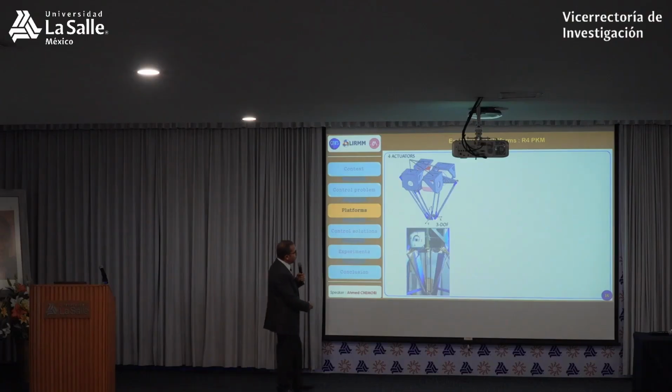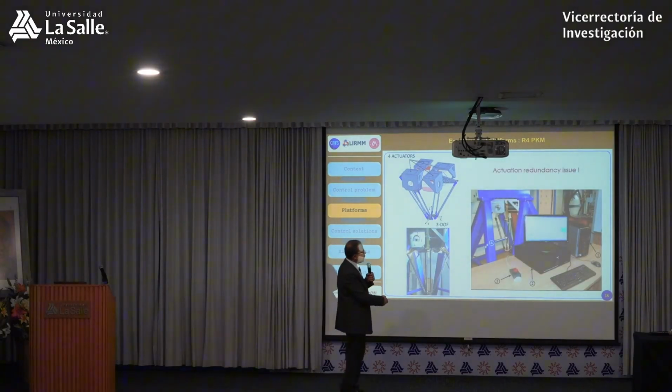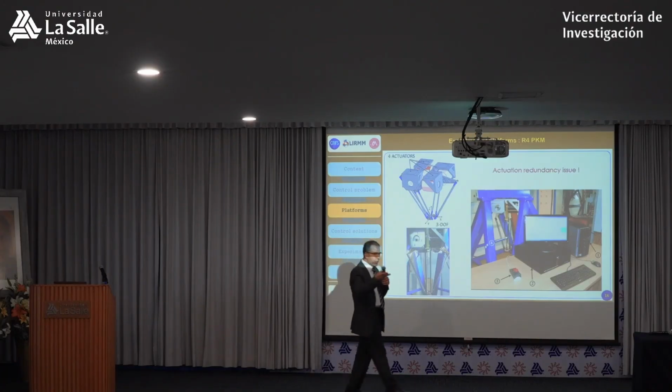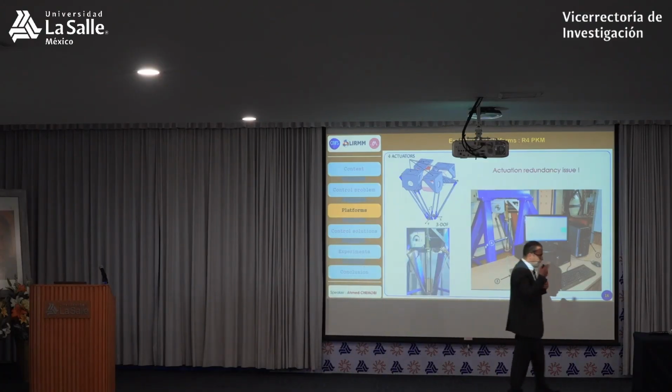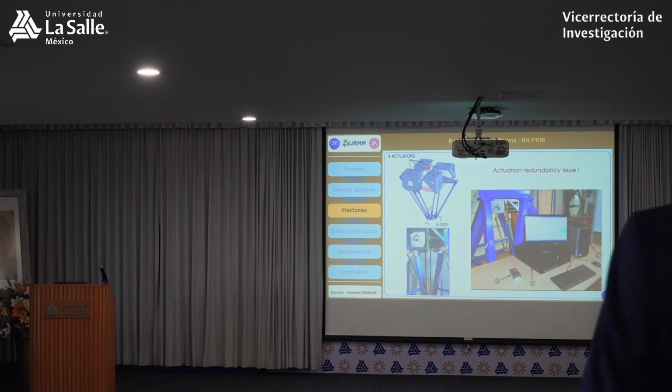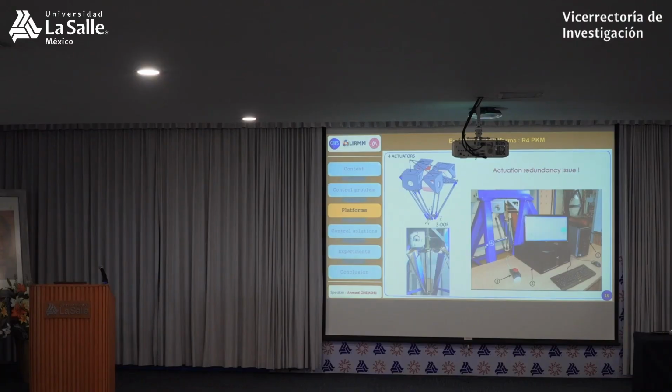This is the experimental platform, and here, as you can see, the whole platform with the mechanical part, with the computer used to control the robot, and here the structure that uses the hardware. It uses MATLAB Simulink with xPC Target as the toolbox that you have used, and you implement your controller on this computer, but you have another computer. You have 2 computers. So the first one here, you have MATLAB Simulink. You develop your controller, and then you compile your controller to generate the C code. The C code will be uploaded on this computer.